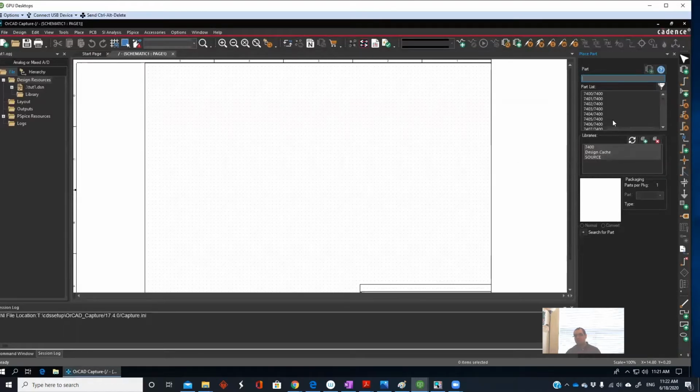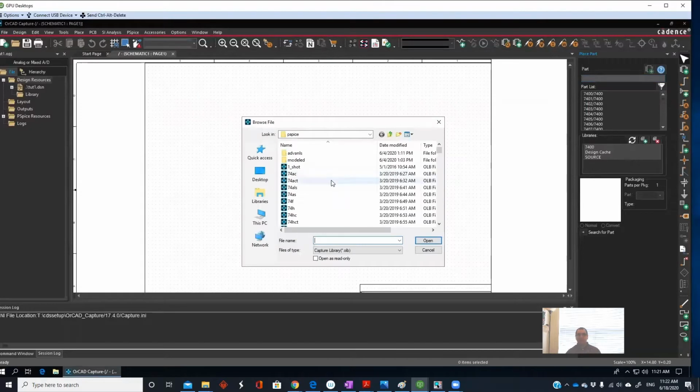But before you add a component, you first need to add something called a library. So if you click here, Add Library, in the first, I would say 2 or 3 experiments, we just need 2 libraries. The first one is the 7400, and this contains most of the ICs we need. I already added them before, but what you need to do is select the 7400 library here. This has all the IC components we need, like all the logic gates.